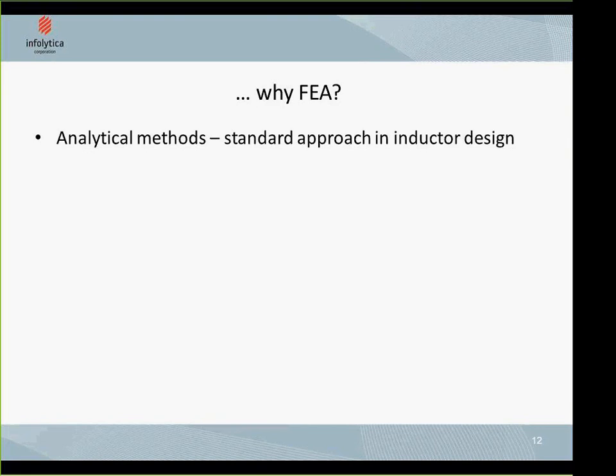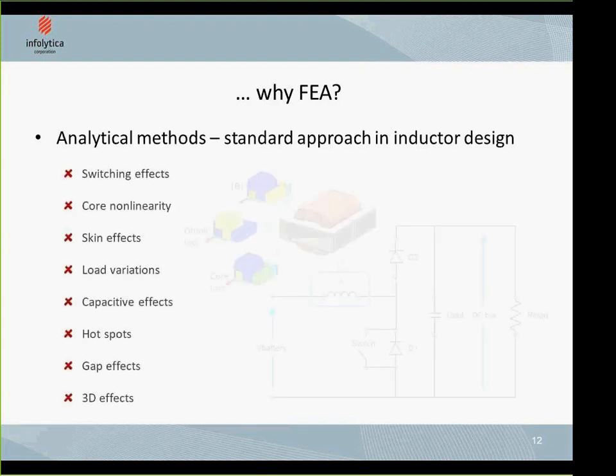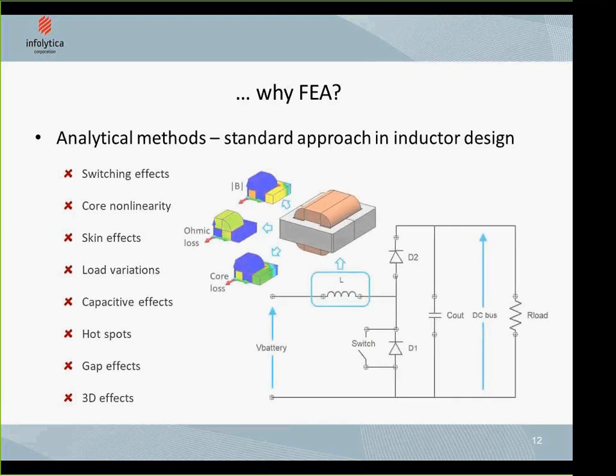Why then do you want to use finite element analysis, or why do you want to use MagNet? The main reason is that analytic methods do not fully account for effects such as switching effects, core non-linearity, skin effects, load variation, fault analysis, and capacitive effects, which require you to use ElecNet to estimate your capacitance. Then hotspots: if you want to see the distribution of your fields and your losses, then it's good to use finite element analysis.